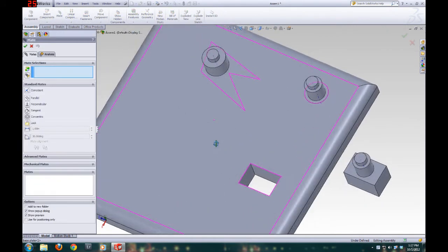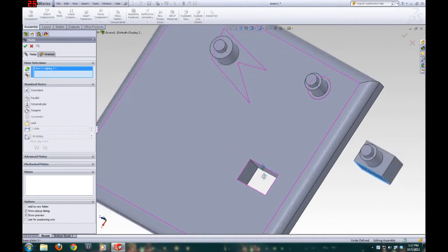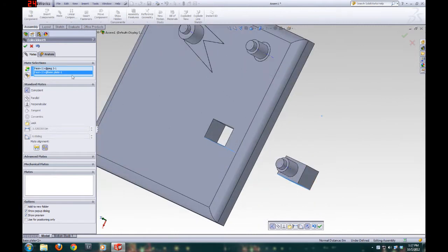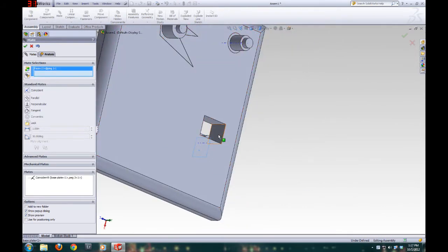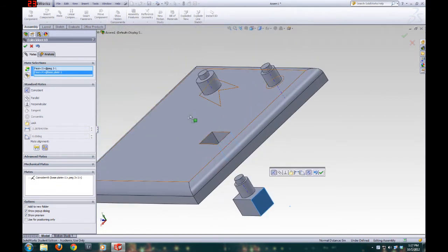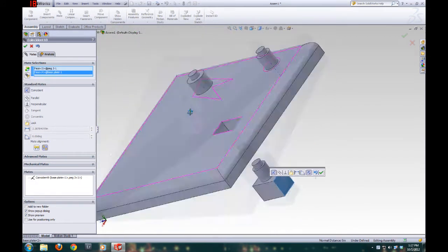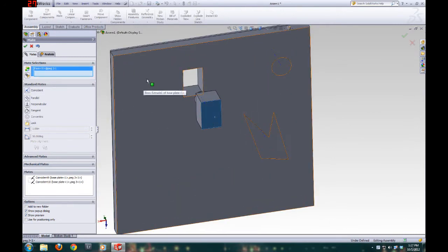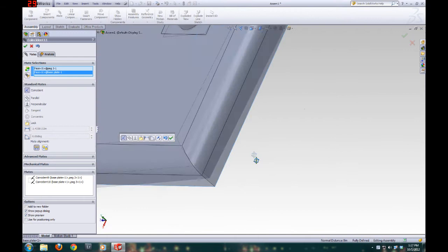Notice it's rectangular, so we'll get this lined up right. This side is actually going to be coincident with that face. We'll say OK to that mating constraint. This side is going to be coincident to that face. Again, you see they lined up. SOLIDWORKS kind of slides apart where it needs to be. Say OK. And then the bottom of the peg will be flush with the bottom of the board.